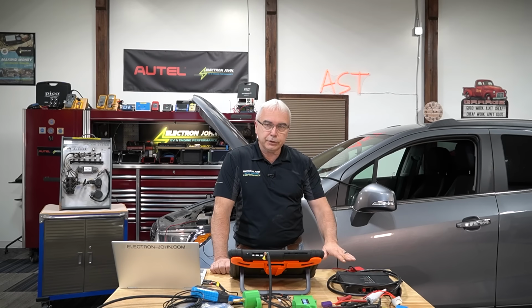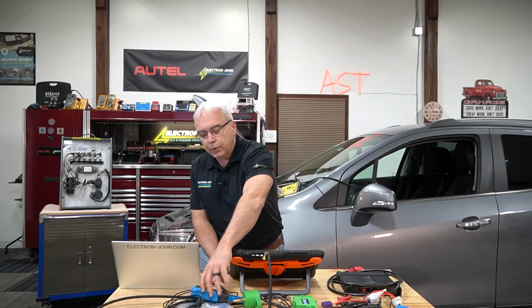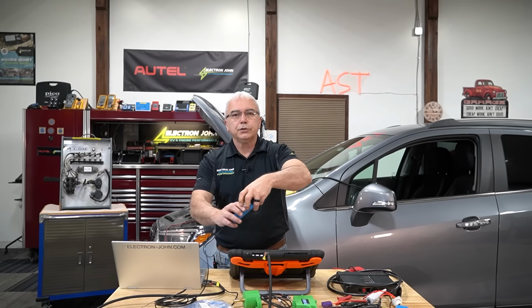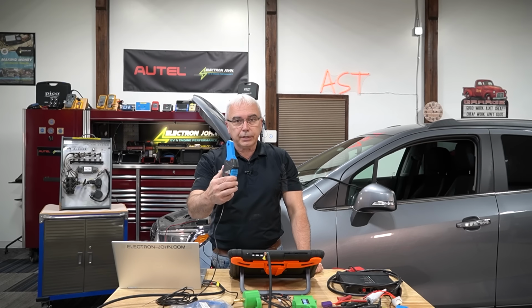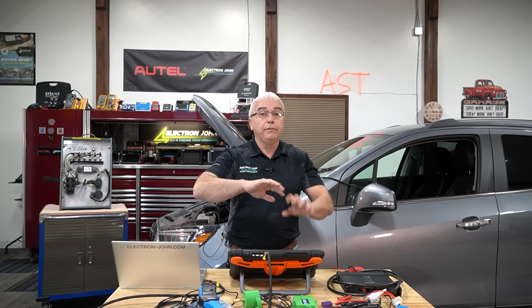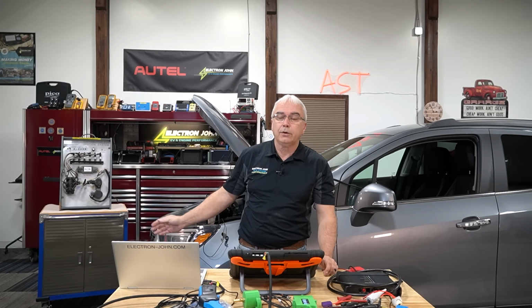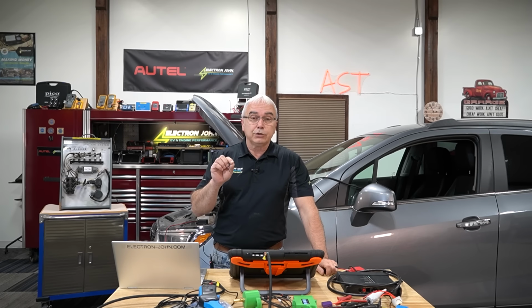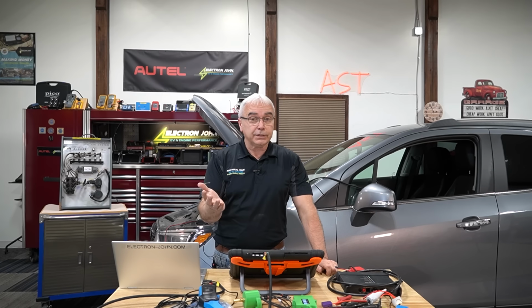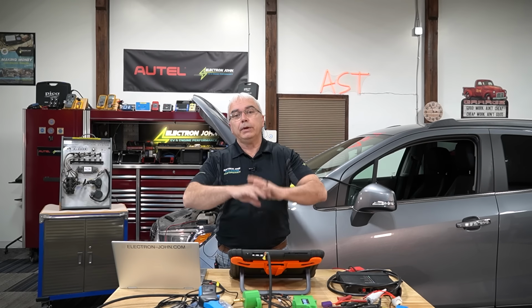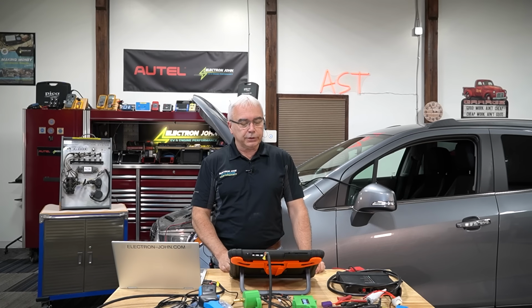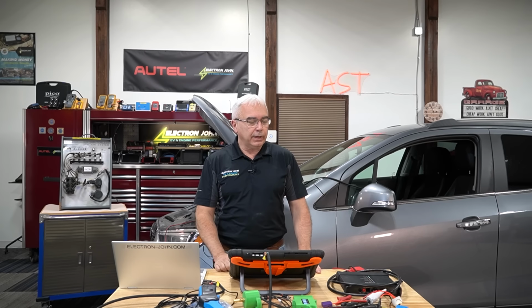And then finally we'll turn channel C on, which is a low amp current probe, which is going to the coil primary circuitry here for all 4 cylinders. This is a 4-cylinder vehicle. So I could select the driver for just cylinder number 1 if I wanted to, but I wanted to get all 4 patterns on there. So that's the progression we're going to make.